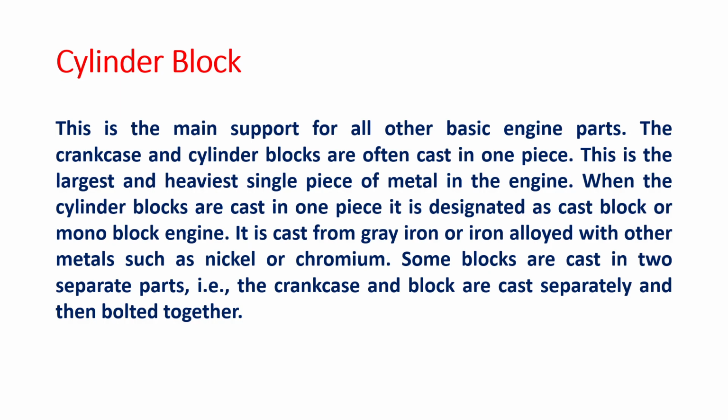So what is this actually? It is the main support for all the engine parts. This is the very largest one, and this will normally be cast in one piece. Sometimes they will be cast in two blocks also. So how will the casting be done? This engine block is normally intricate.